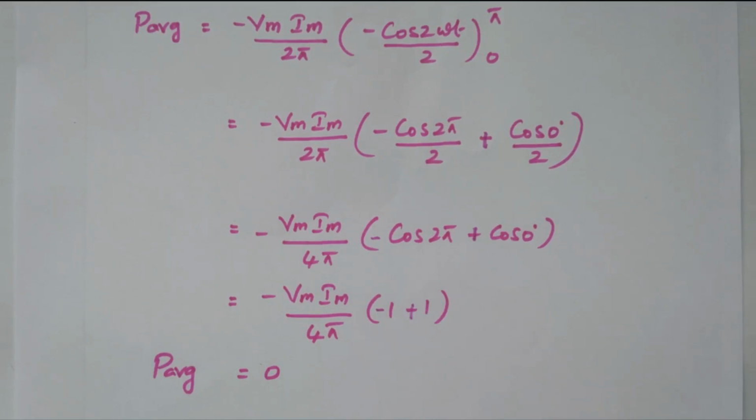So in this video, we discussed when the alternating current is flowing through the inductor, what is the behavior of voltage and current. We identified that current is lagging the voltage by 90 degrees. And also we got the expression for instantaneous power and average power. Thank you.